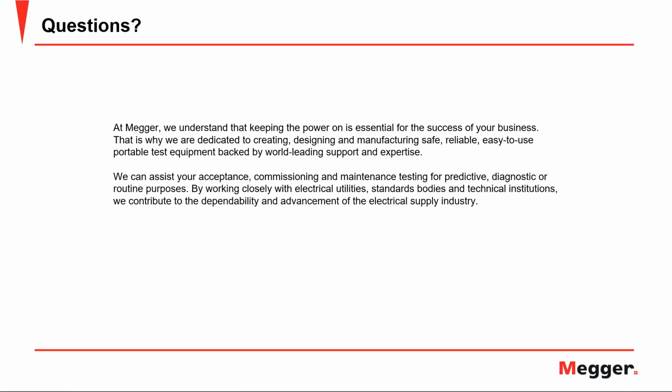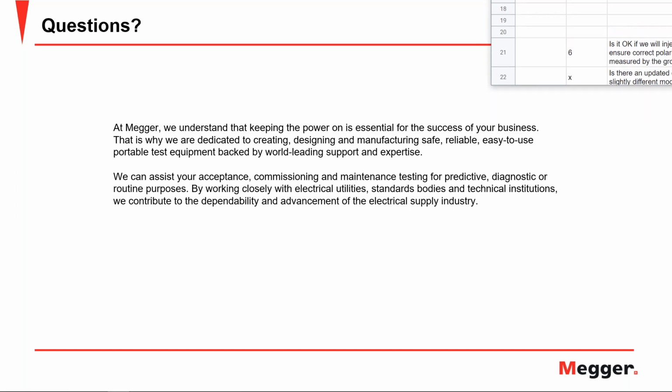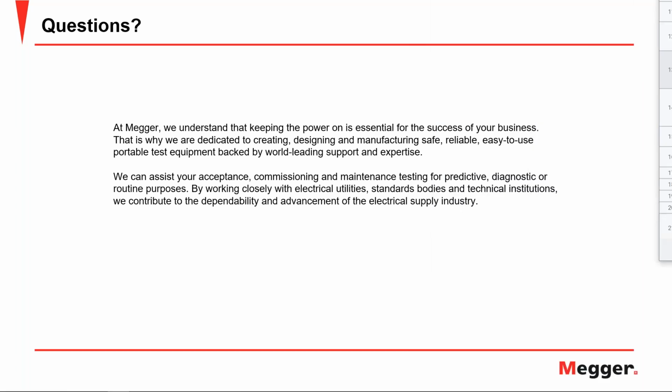So the TCC is the time current curve, and the time current curve comes from the manufacturer of whatever device you're testing, whether it be a ground fault relay on a voltage pressure switch, or a circuit breaker with the external neutral CT, or whatever the application may be. Daniel gave many different examples. And what that time current curve has is a plot of the interrupting times for an overcurrent device based on a given current level.